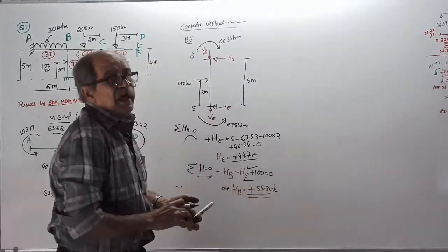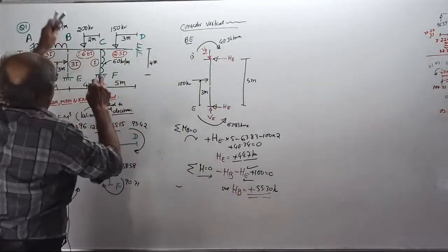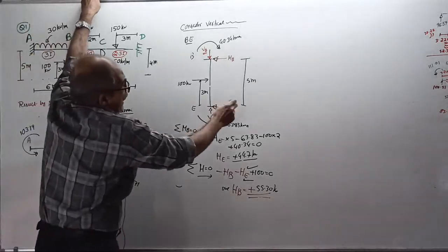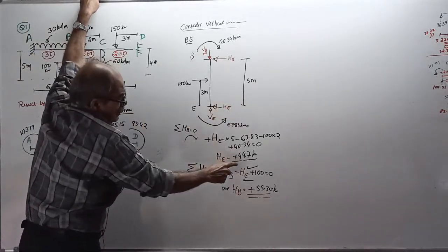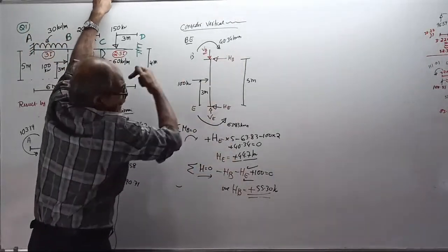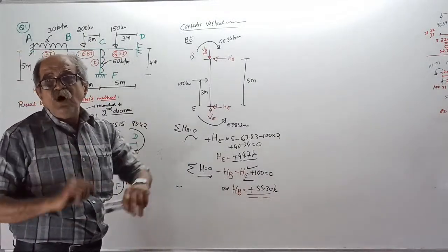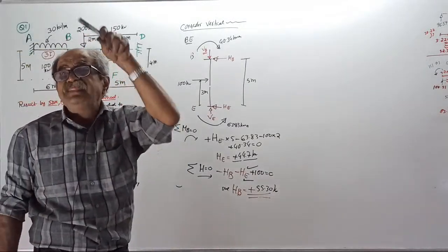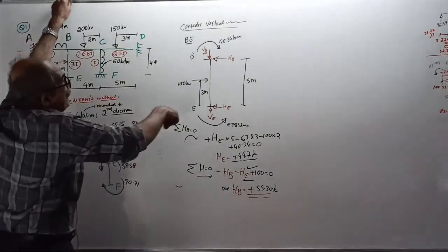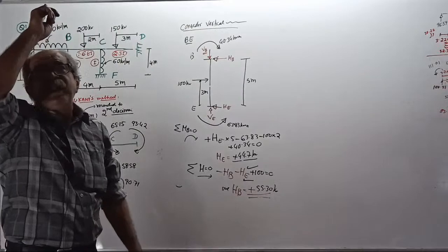Therefore, when I put the free body for this column later, what will I do? At the base, I will mark a left side reaction of 44.7. At the top, I will mark a left side reaction of 55.3. And also, for those who are in the group, I will apply a vertical load of the sum of those two, VB1 and VB2.